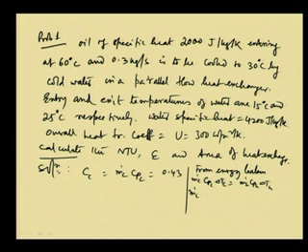So, m dot C is equal to 0.3 into 2000 into delta Th, which is 30 because it is 60 to 30, divided by Cpc equal to 4200 and delta Tc equal to 10. So, this is equal to 0.43 kg per second.